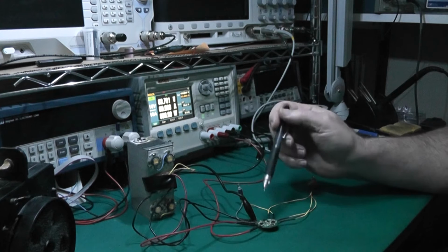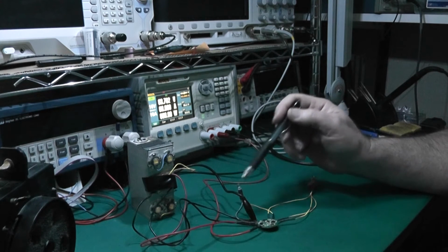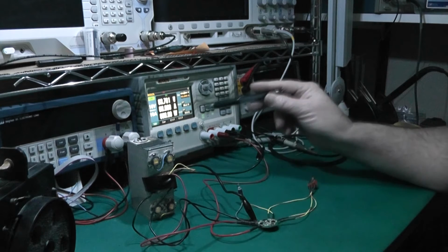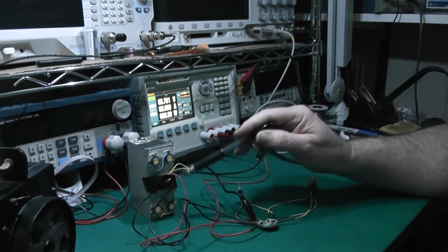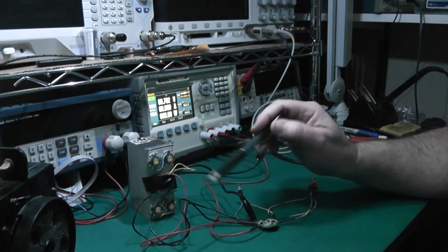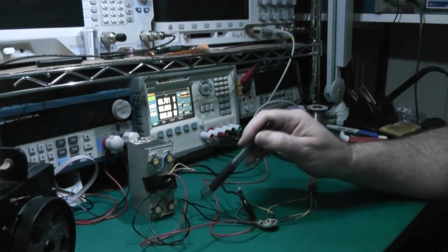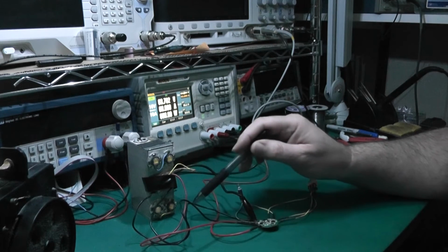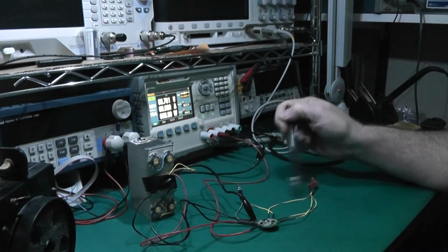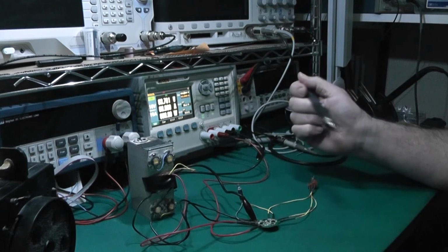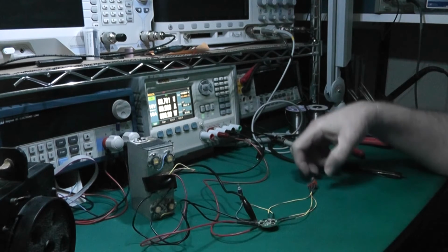We have the Dualflex driver, status LED hooked up, power coming in from the power supply, and then our two LEDs. The two LEDs are wired such that there's a single positive feed and the two individual controlled ground feeds, and we have our switch center ground and the two contacts. So right now it's turned off, and so I'll turn it on.